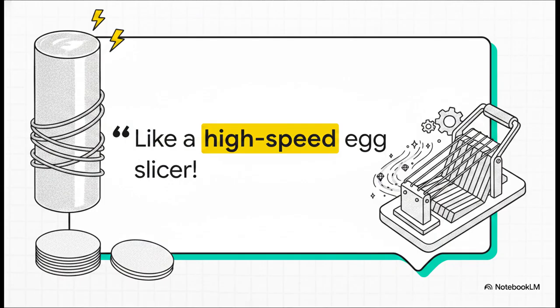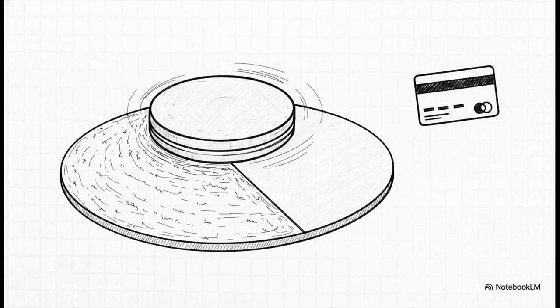The diamonds gently grind their way through the hard cylinder, slicing it into lots of incredibly thin individual discs called wafers. And when I say thin, I mean absolutely paper thin. These wafers are roughly 725 micrometers thick. That is right about the thickness of a standard credit card you'd find in your parents' wallet. But the wire saw leaves microscopic scratches on the surface, and we need this surface to be utterly flawless.